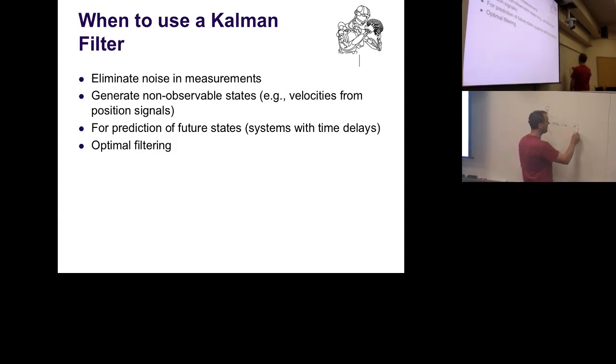Now you have to use this stuff to actually figure out where that base is. Since it's not measured, we cannot put a position sensor on this robot which measures absolutely where it is and how it's oriented in space. So we would like to know x and usually a quaternion q for the orientation. So this is a quaternion.